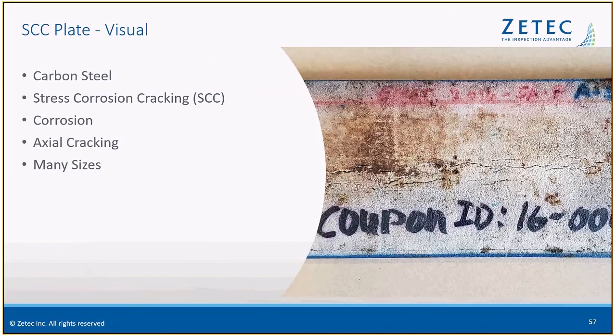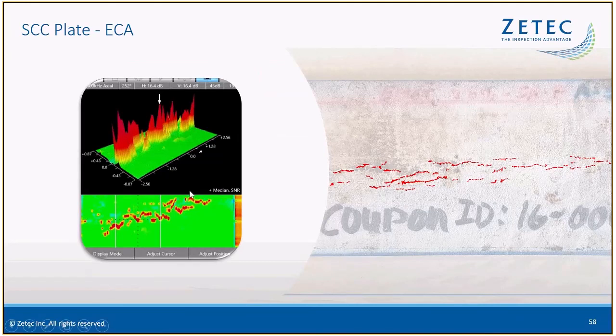This is another example of stress corrosion cracking in carbon steel. And this is a very problematic type of defect that can occur. In this case, there's heavy axial cracking happening with many sizes along this plate. And using the eddy current array, you can see all this axial cracking that's occurring. Highlighted here with an overlay of the palette C-scan, you can see exactly where those cracking indications are occurring. So you're giving that exact information, able to do size and scale of the cracking.